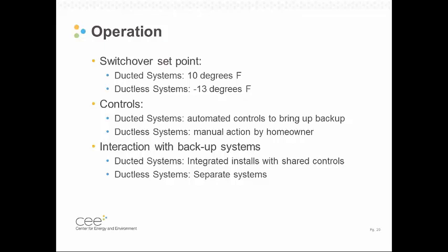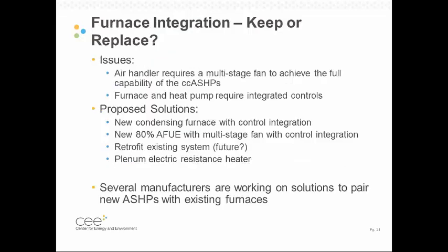And so as the heat falls in the home, and it's getting cooler and cooler, and it hits 70 degrees, the heat pump system knows to trigger and starts to heat up the home, and we don't hit that 68 degrees, so the electric resistance never kicks on. And so the heat pump will be the primary system. As you move beyond the capacity of the heat pump, the temperature will drop below that 70-degree point if it can't keep up, and then once it drops down to 68, the electric resistance thermostat will see that temperature difference and kick on to become a supplemental heating system. So it's a slightly different method of operation, but achieves much the same effect, where the heat pump is the primary means of heating, and you have a backup heat source available when there isn't enough capacity.